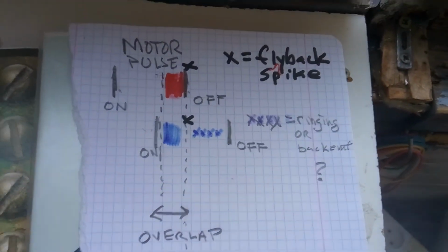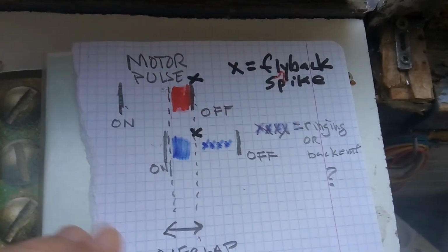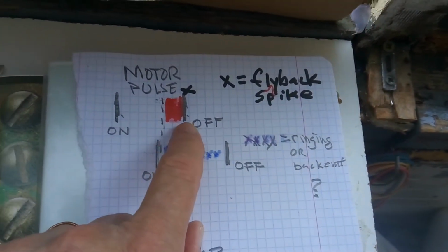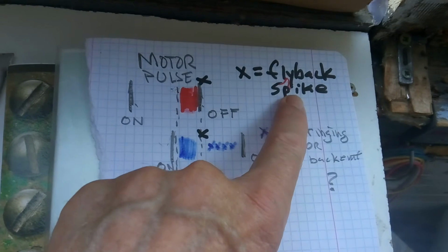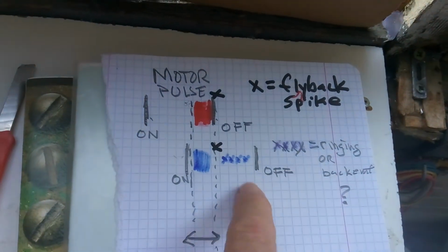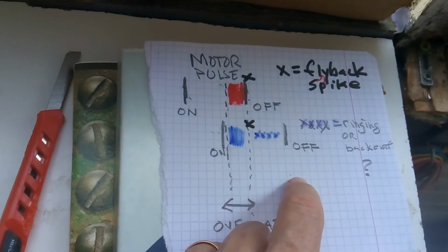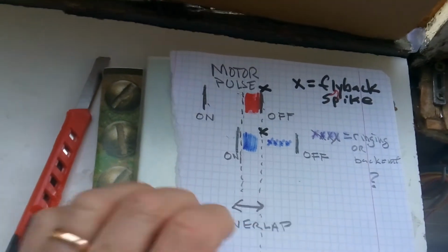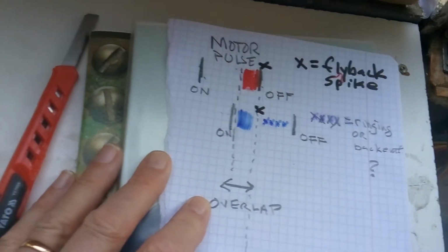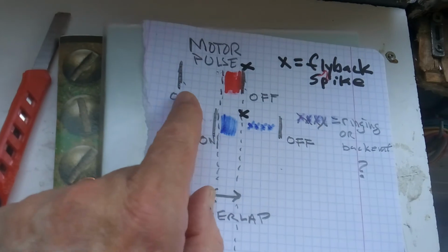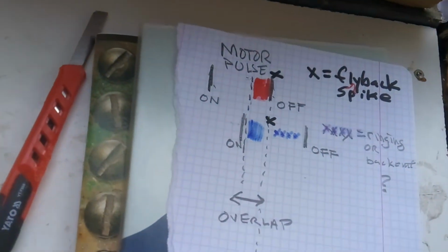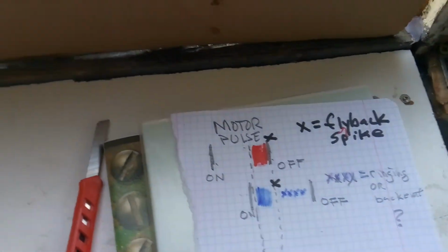Again, I'm not talking about Lenz's law here. I'm just talking about collecting the flyback spike. And you know, if you short out the flybacks, this flyback spike, the steering diode going into capacitors, you just short it out without decoupling the motor coil pulse, it'll really cause problems.